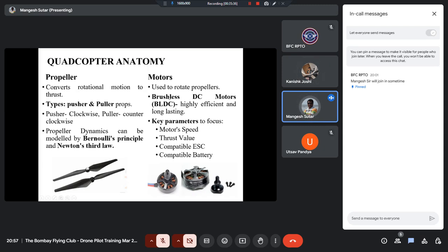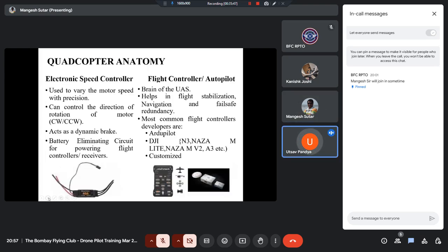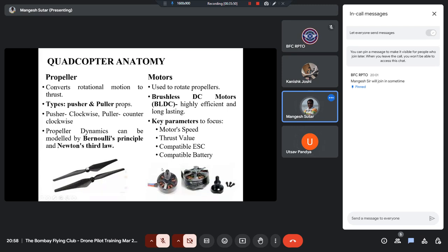This has brought a lot of efficiency in the motor movements. Where are the magnets in the BLDC? On the circumference, the outside part. Even in the DC motor, magnets are outside. The layout of both motors is similar, but in the DC motor the armature which rotates, the coil, is actually rotating. Since the coil is rotating, you cannot give a fixed point to the armature.